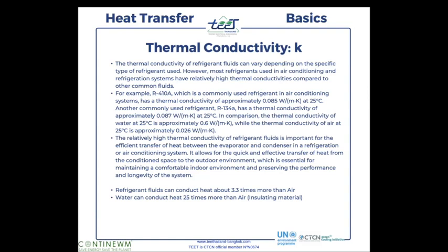So these are some examples. You don't need to remember everything by heart, but it's just to give you an insight and a culture of what is happening in air conditioning. So for example, R410A, which is one of the refrigerant fluids commonly used in air conditioning, has a thermal conductivity of about 0.085 watt per meter Kelvin at a fixed temperature of 25 degrees Celsius, okay?